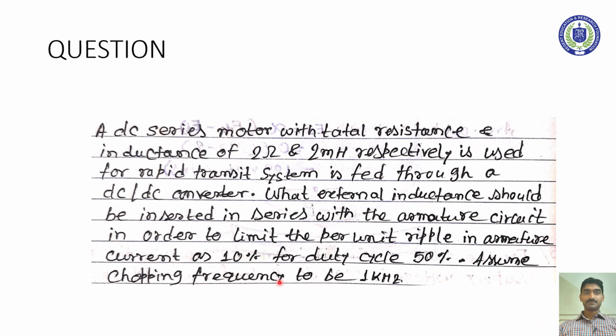Also, it quantifies how well the converter is able to filter out the AC component from the switching process and provide a smooth DC output, because any output consisting of noise or interference is considered lossy, which we do not require. A lower ripple factor indicates a cleaner DC output with less AC variation.